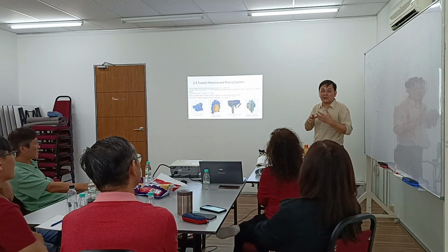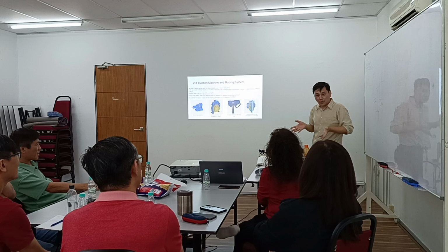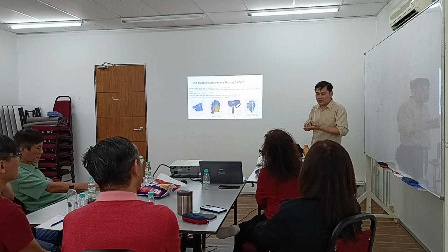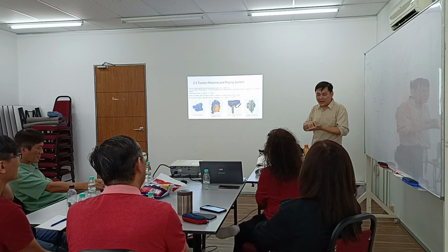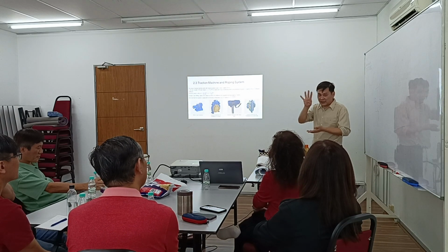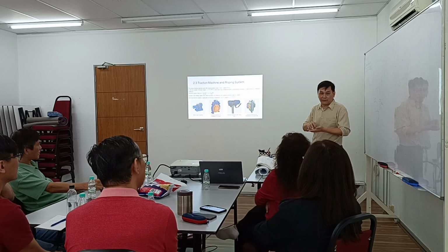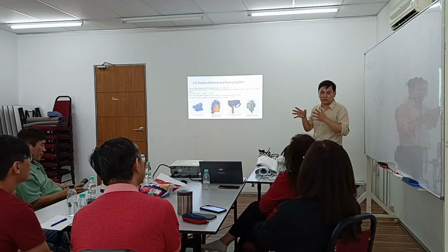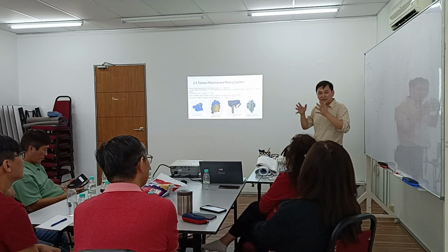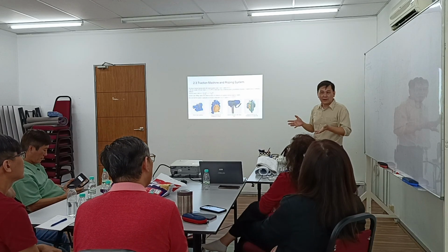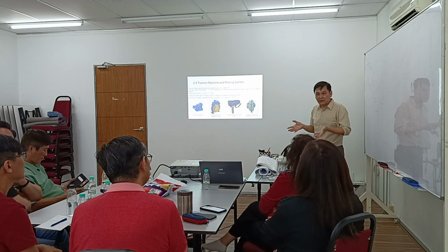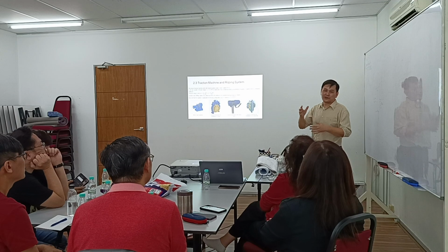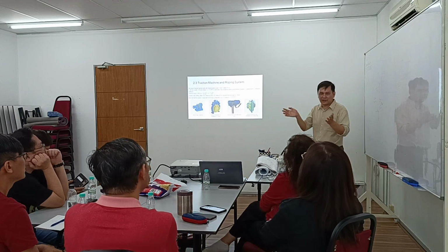So that's why when we look at the sheave of the motor, they also have some criteria. If your rope diameter is 10 mm, your sheave diameter must be at least 40 times. That needs to be 400 mm. So that is also the criteria to double check. But the sheave diameter also cannot be too big because the bigger the sheave diameter, the higher the moment. So you require higher torque. So there are many design considerations and trade-offs.